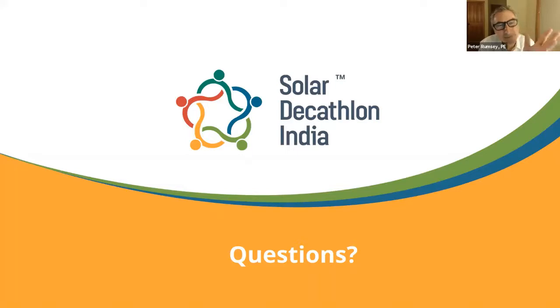So there is this question of what day of the year that occurs, and what time of day. The sun at noon is high and then it starts coming down. Sometimes the maximum cooling load is when the sun is coming down, at 3 p.m. or 4 p.m., and the sun is coming in the window. So when we're doing a load calculation, we'll test two or three times during the day and use a temperature that's relatively appropriate for that time of day. The software packages will test every hour of the year and find where the maximum is.